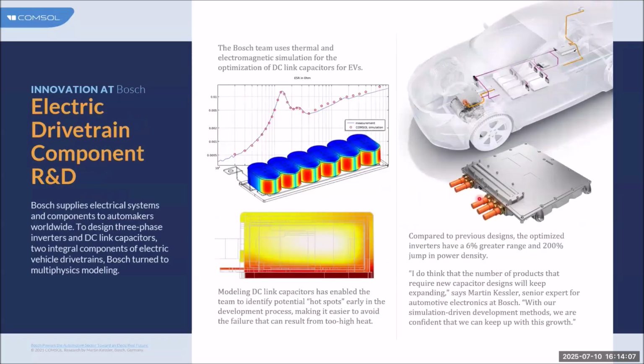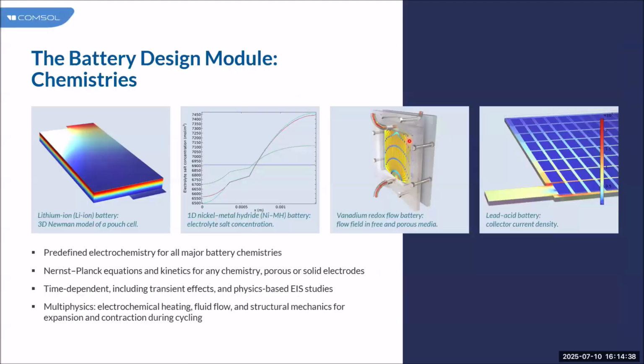And in another case from the power electronics sector, in inverters, Bosch is utilizing COMSOL to understand or model the ESR, or the frequency dependence variation of the DC link capacitance. That is one thing with the EM part, but they are also trying to understand the hotspot temperature development inside the DC link capacitors or the overall design, and how to mitigate it using design variation and optimization. So this way, industries use COMSOL in various aspects of the EM drive.